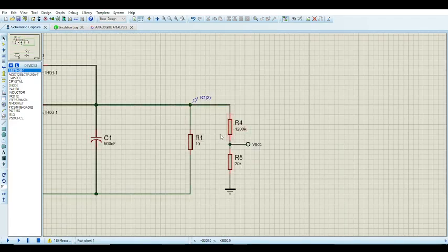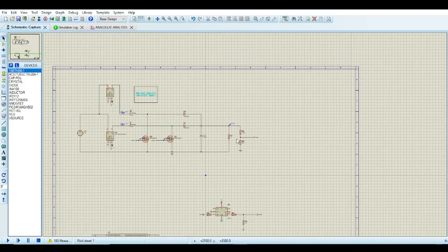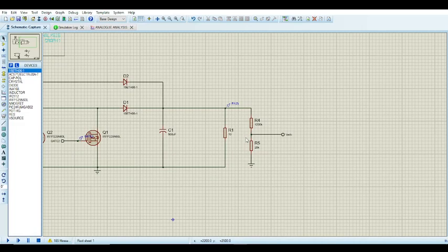And also for this part here, the voltage sensor, this is also important. In the real world, you'd actually add a capacitor in parallel to that, sort of 10 nanofarads, depending on what this resistance is. It's a low pass filter of sorts. You add a capacitor here because resistors are not so perfect in the real world, and noise is a thing as well, so you're going to have to deal with that.